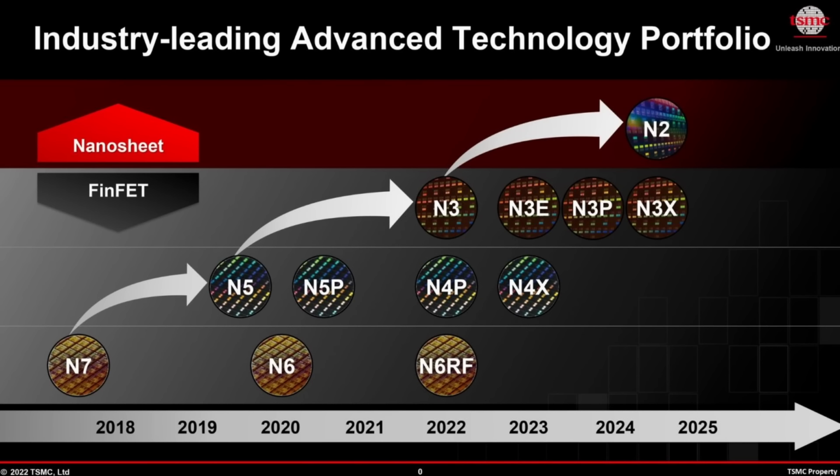There are many different types of logic gates. The most common ones perform operations like AND, OR, NOT AND, which is also called NAND, and many more. Don't worry, you don't need to understand how they work in order to understand FinFlex. Logic gates are first described as technical diagrams, but in order to do actual work, they have to be built by using transistors. And that's where the CMOS FinFET transistor comes in. Based on the electrical diagram of the logic gate, transistors are combined in such a way that they perform the same function as described by the electrical drawing. For example, only generate an output when 2 input voltages are the same.